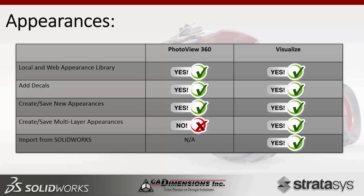Visualize, however, does have the ability to create multi-layer appearances, which is pretty cool. What that allows you to do is stack appearances together. So for something like carbon fiber, which is what I've been using it for very nicely, you can create that texture underneath and then a clear coat over top or something like that. So you can combine appearances to really get the visual properties that you would expect to see if you were looking at it with your eye. You can create and save those as well.